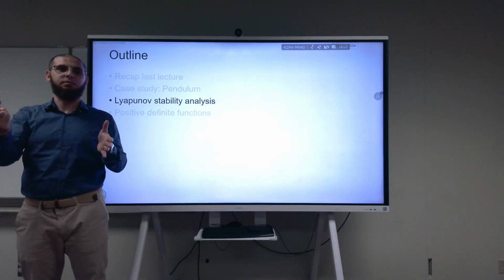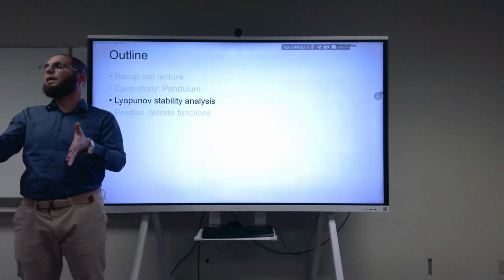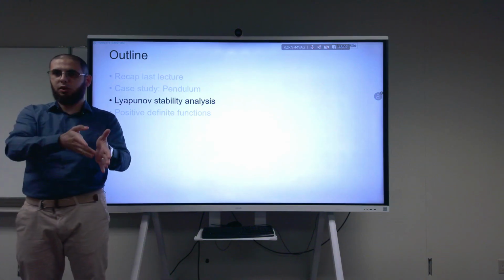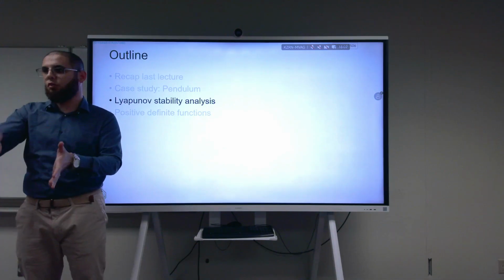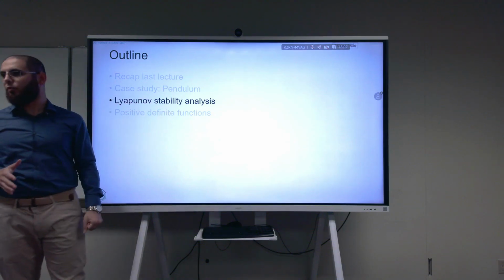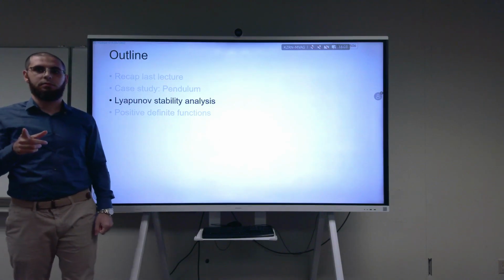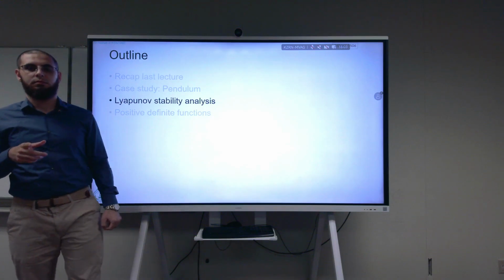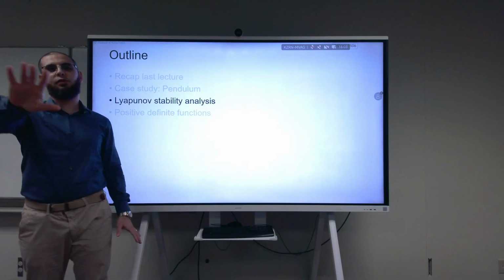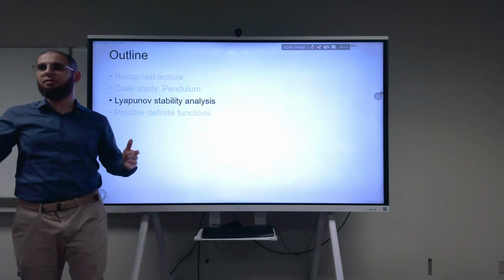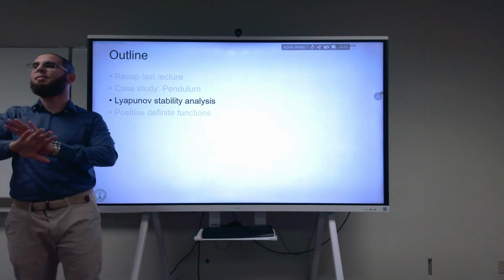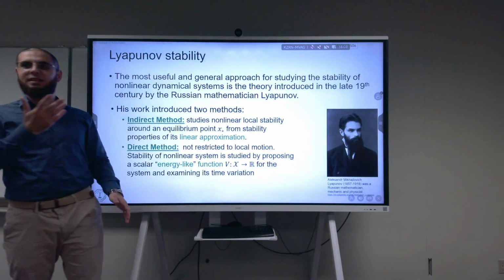If I have a 2D system, for example theta 1 and theta 2, then the phase space will be 4 dimensions: theta 1, theta 2, theta 1 dot, theta 2 dot. So it's already 4D, and I cannot visualize it. This is too limited, only for toy problems. But we can use a phase portrait for a combination of different states. Then we go through a lot of effort just to visualize a 2D system. Can't you visualize it in 3D? Do whatever. The best you can do is a two-link manipulator. But this is not what we actually use.